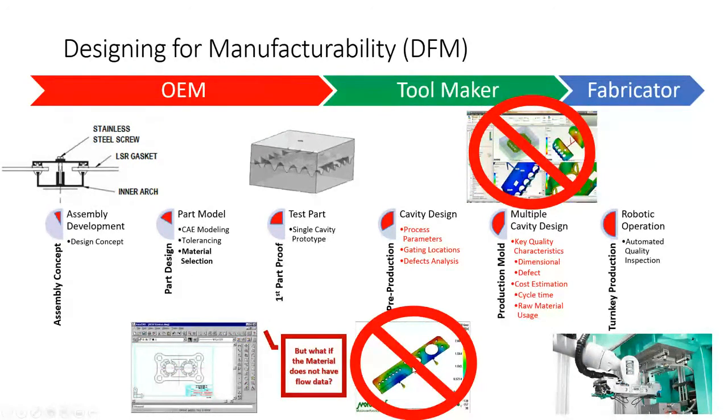You make a tool, it doesn't work, it becomes the so-called boat anchor, meaning it didn't work, so tie it to a rope and throw it off of a boat, and you can keep the boat. Well, definitely a wasted expense there. Keep in mind that tooling in some cases can be multi-million-dollar items. So you want to be able to do it right the first time. Speed to market is very critical there. If you don't follow that program of looking at how to design the cavity correctly, you're definitely going to run into issues.